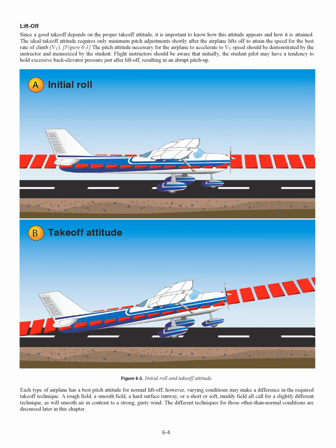The pitch attitude necessary for the airplane to accelerate to Vy speed should be demonstrated by the instructor and memorized by the student. Flight instructors should be aware that initially, the student pilot may have a tendency to hold excessive back elevator pressure just after liftoff, resulting in an abrupt pitch up.